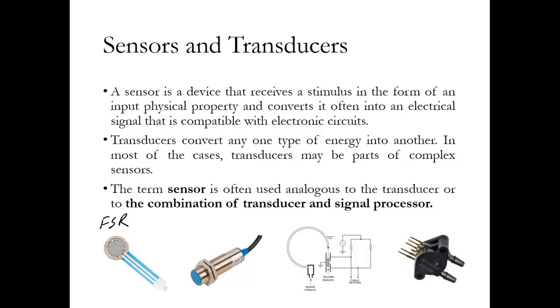This is how it looks as a pressure sensor, but rather than using a Bourdon tube, we use piezoresistive sensors or other types of semiconductors. It is a diaphragm whose deformation we are able to measure. We'll talk about those types of circuits and sensors. But this is how a typical industrial or commercial pressure sensor looks. This is used for differential pressure measurements. So these are some of the sensors that we usually see in our day-to-day life or in industries.